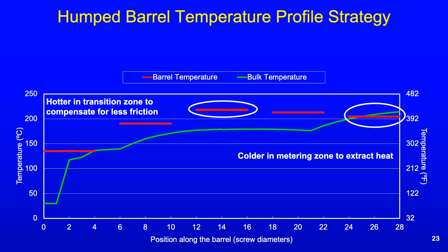And if you don't have a melt temperature probe, in this case they didn't have one that worked, I add at least 20 degrees Fahrenheit to whatever the last zone temperature is, assuming it's going on and off at a regular spacing. In this case, I set it up so it's going to be more on cool than on heat.